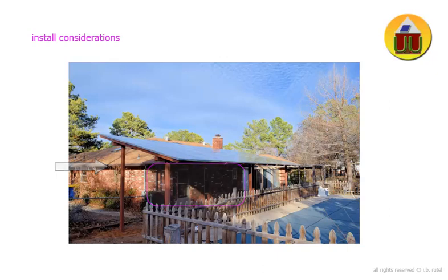Finally, you will want to look around and survey the obstruction issue. Trees tend to grow, and what you may consider as no issue upon install can become a major obstruction in several years. As a footnote, your install may be determined by the proximity to the breaker box for the grid tie system. If your run is too long, you may incur higher costs for long runs of large copper wires or require a separate visit by an electrician to provide proper connections.